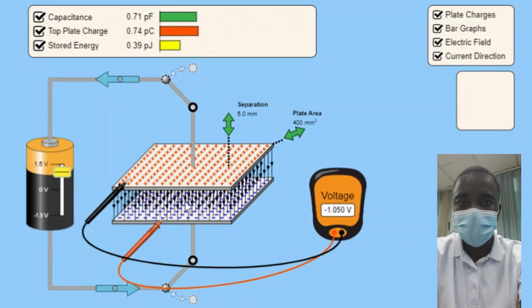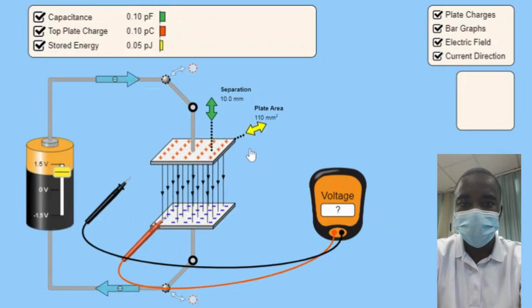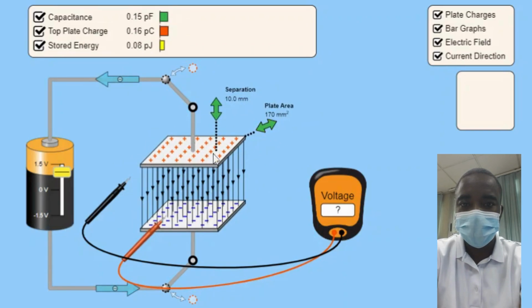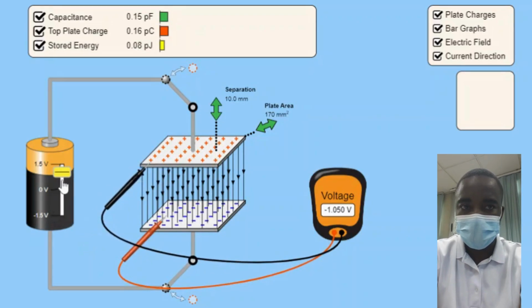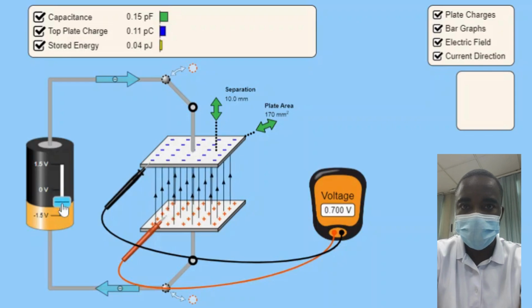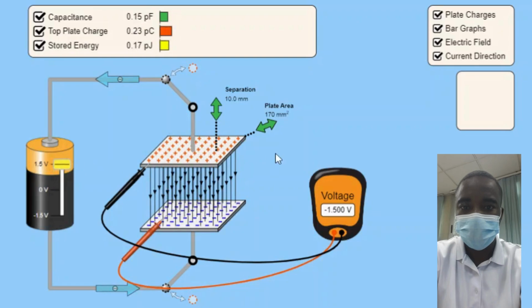Students can observe the discharge process of the capacitor in real time. As the capacitor discharges, the voltage across it decreases exponentially, and the current through the resistor also decreases. The light bulb's brightness diminishes over time, providing a visual representation of the discharge process. This interactive feature helps students understand the dynamics of a discharging RC circuit and the behavior of capacitors in electrical circuits.